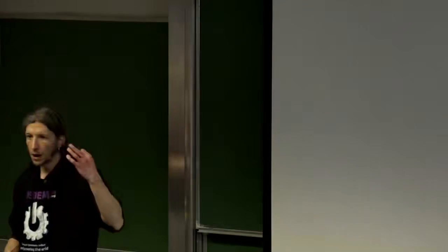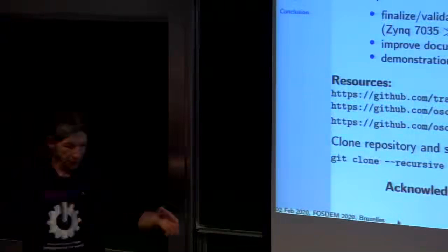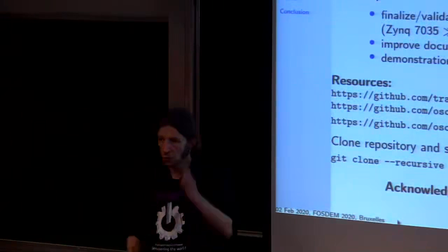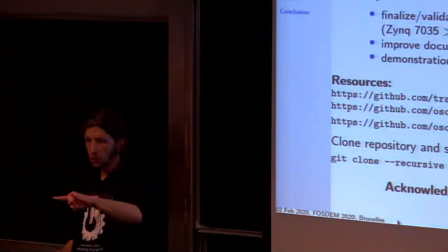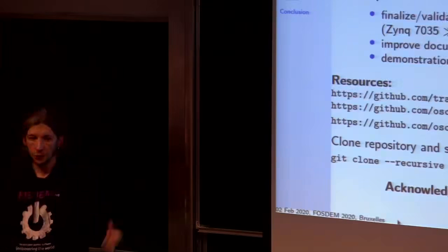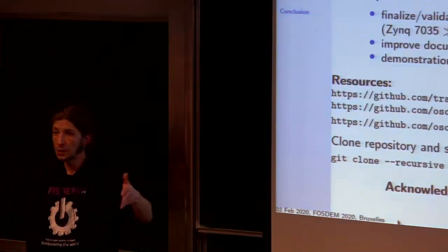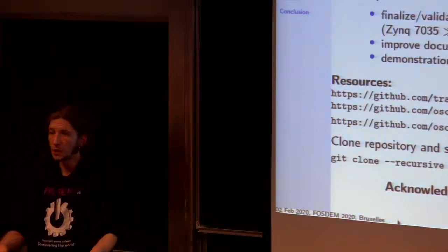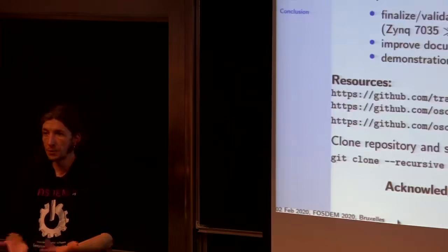Finally, in the FPGA, we are just limited by the sample rate. If the sample rate is 1 mega sample, we have 1 microsecond between two new samples. If you need to cross-correlate about 1 kilopoint, you have just 1 millisecond. It's not possible to reduce this because it's the RF front end, the limitation.